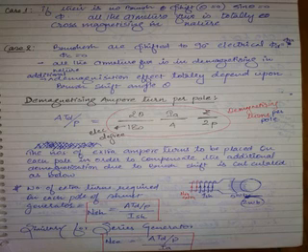Make a note here again. If brushes are shifted to 90 degrees electrical, if you substitute in phi a sin theta, you will get phi d is equal to phi a. In phi a cos theta, you will get phi c is equal to 0. That means all the armature flux is demagnetizing.